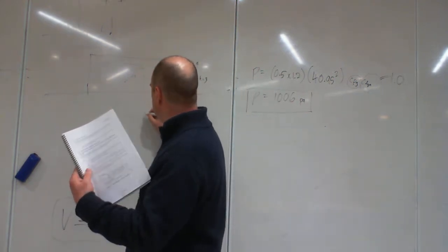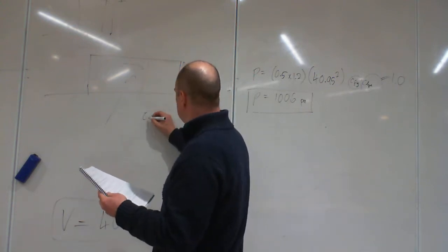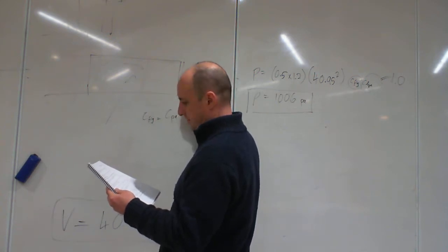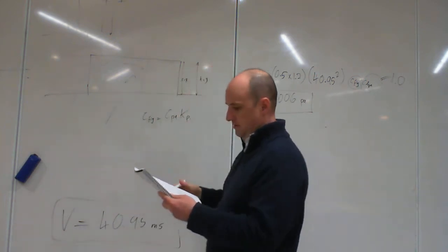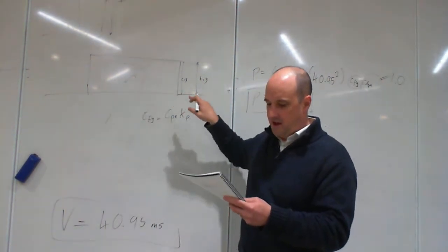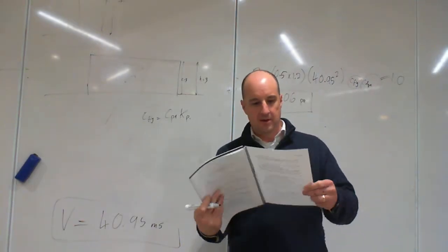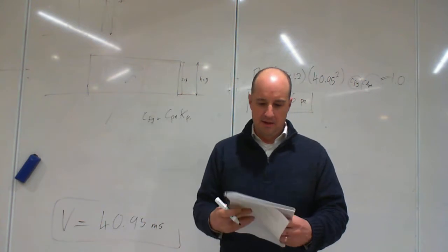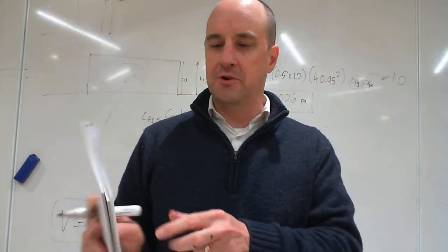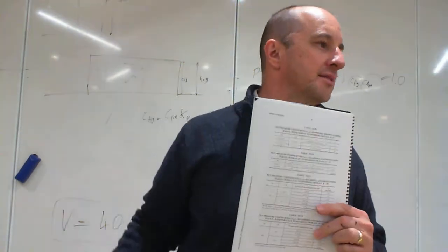from D2, when I say D2 it's Appendix D, Clause 2. C fig equals CPN times KP, where CPN is a net pressure coefficient acting normal to the surface, and Kp is a porosity factor. Alright, and we look at a table here, we can see net pressure coefficient, hoardings and freestanding walls, wind normal to the wall or hoarding with an incidence of 0 degrees, as in the wind is blowing against the wall.